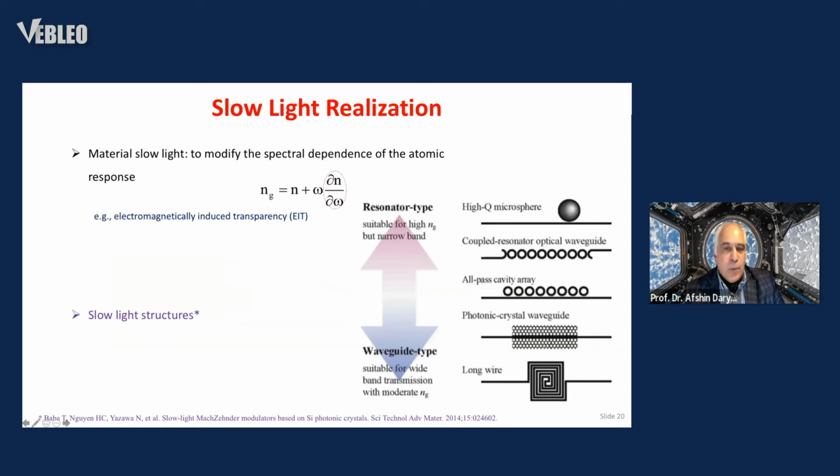What we have done is we have taken those approaches and modified them by using the slow light effect. The slow light effect is based on a dispersive characteristic of the index of refraction with the operating frequency. So rather than being in a TEM mode of propagation, you have a non-TEM mode, and you have a dispersive characteristic due to the periodic structures of the slow light wave structures. And it has been used for a number of applications, including the delay line.